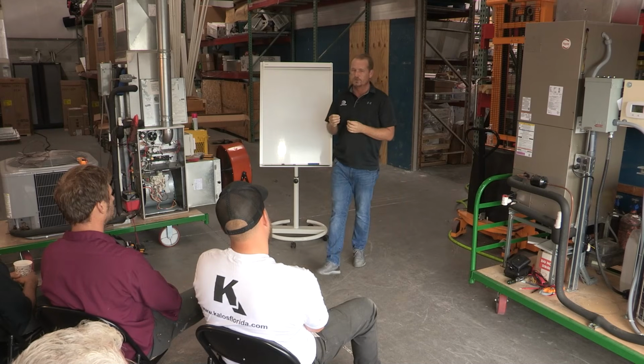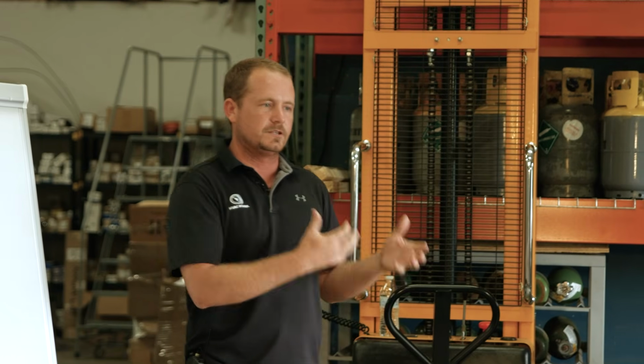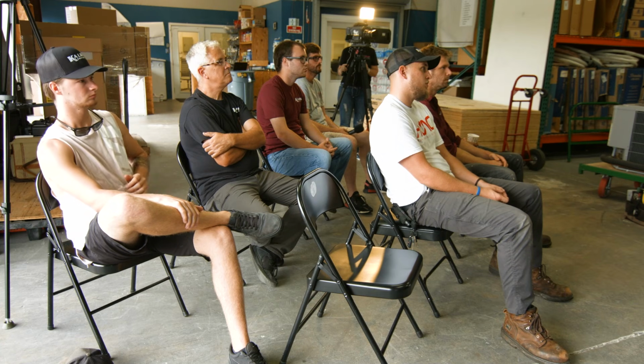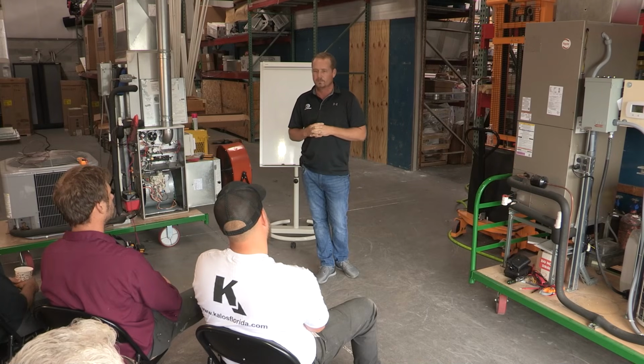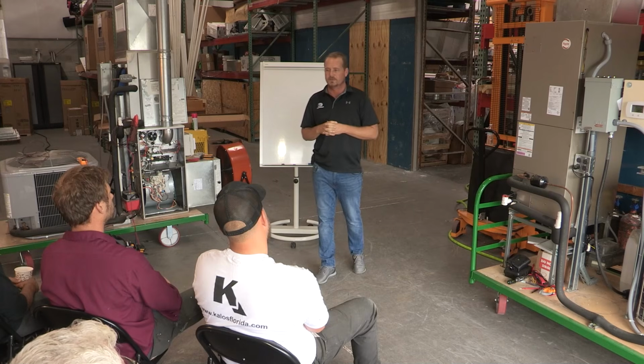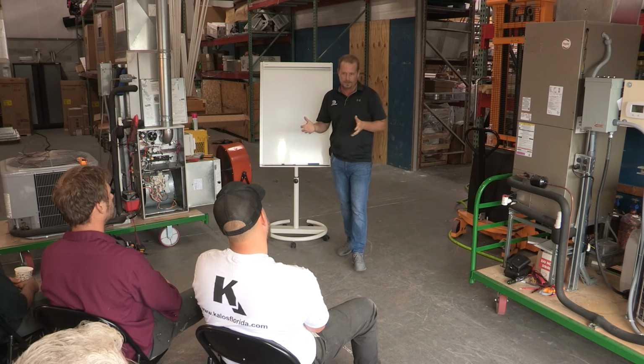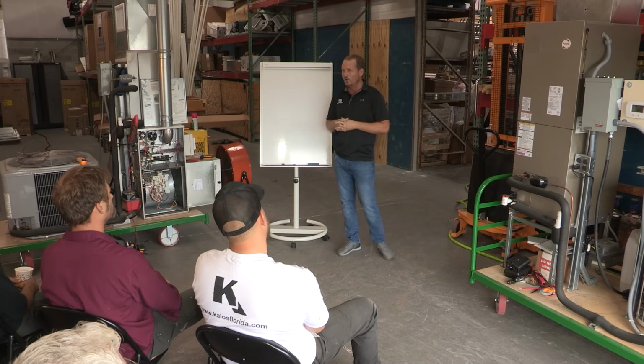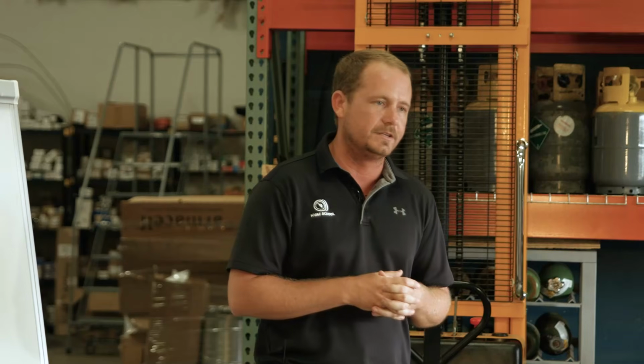And so a lot of what we're doing is making sure that we're connecting things in the right places so they go to the right spots. In terms of an installer's responsibility, in terms of a service technician's responsibility, so much of what we do comes down to that. I think with ductless systems, they talk about how, I'm making this up, but I think I heard this at one point, 70% of the problems with ductless systems have to do with the electrical wiring being done incorrectly. Crossing wires or not making good connections. All the time, those are the sorts of problems that we run into.